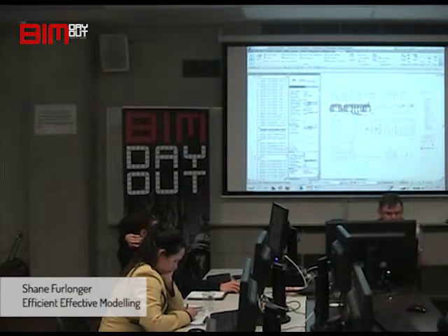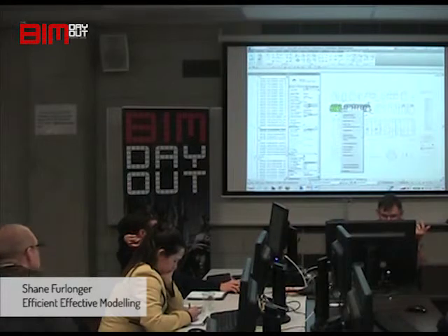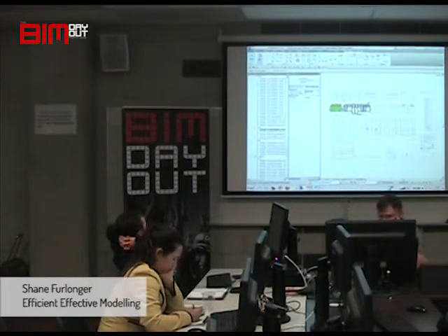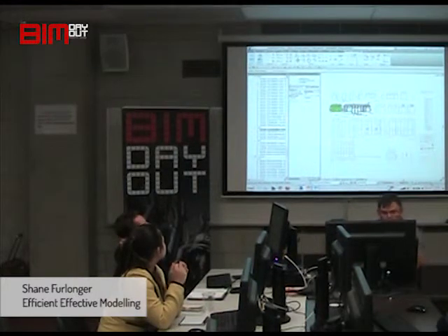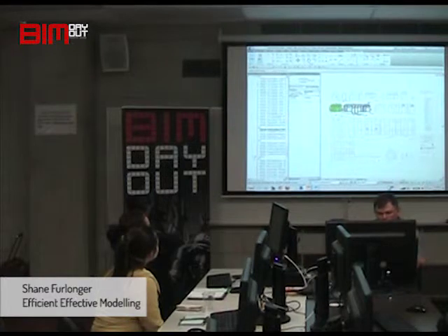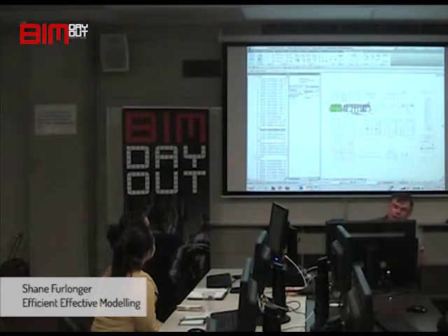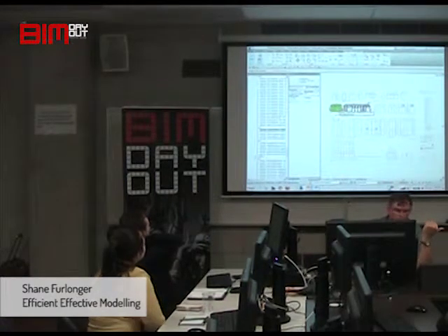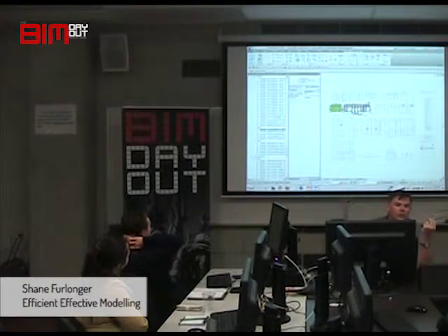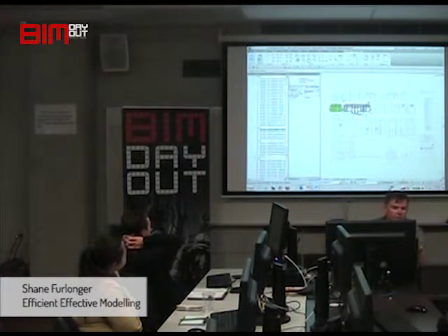These elements are also in the model. So if I clicked on one of these and said select all instances, it should be two, yeah. So there's two of them. One in the legend phase and one in the model. I can make a change here and it'll automatically reflect in the model. But this item, which is in the legend phase, won't show up in any schedule that I create for the model because it only exists in this legend phase.